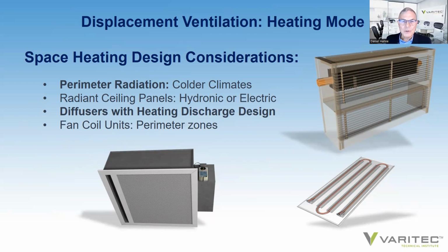This is the solution that was used at the Banner Boswell patient space renovation project, and we never had a thermal comfort complaint using this solution. Using ceiling displacement ventilation, however, you will not gain the advantage of the 1.2 ventilation effectiveness mode offered by standard 62.1. So be aware of that. But it does offer you a lower first cost because you can run flex duct to these devices, which is a cost savings versus running sheet metal duct down in walls to low in-wall diffusers.